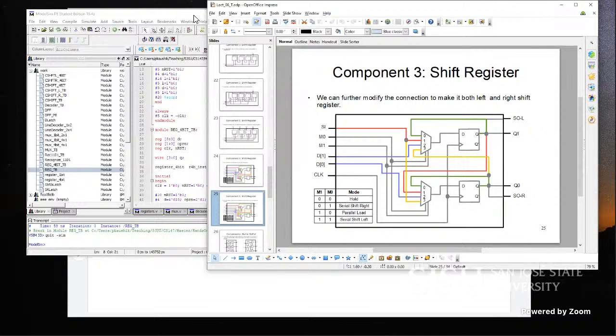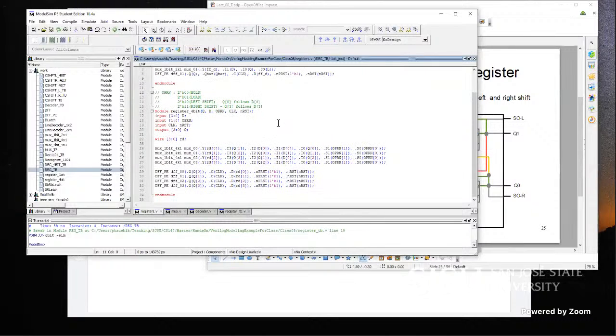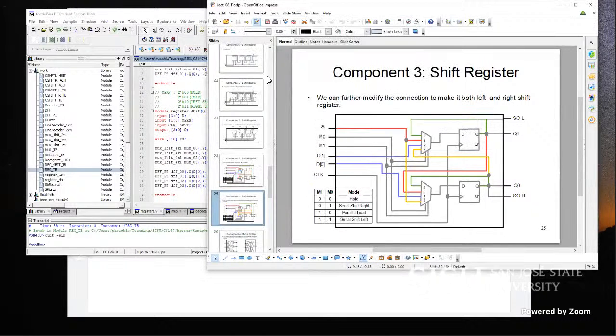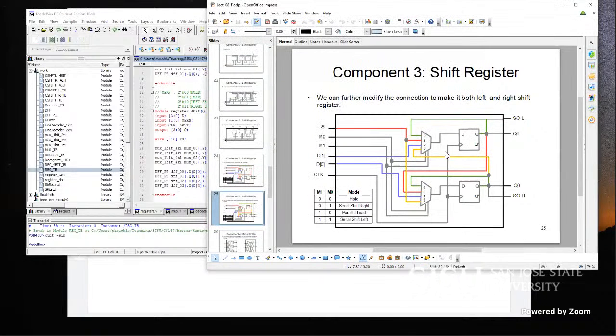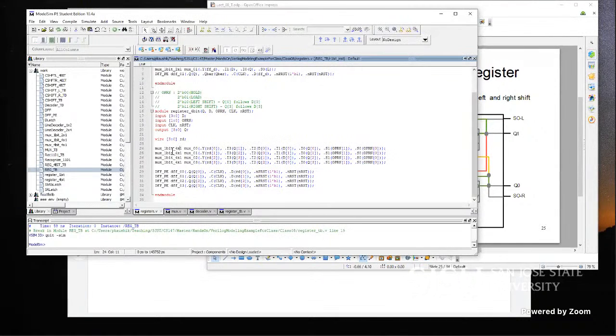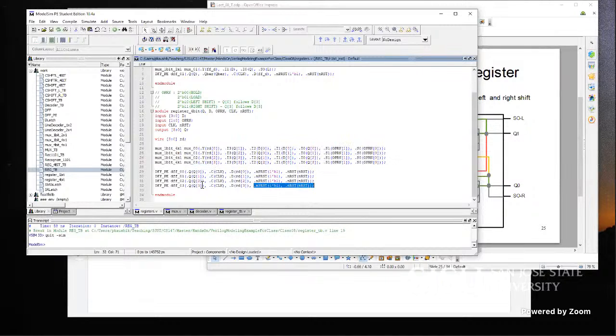Let's try to define it in Verilog, where it's a little bit different than the one proposed here. First of all, it's 4-bit, just to make the life interesting and observation interesting. So that means it has four 4x1 multiplexers, 1 bit each, followed by the 4 positive edge D flip-flops.